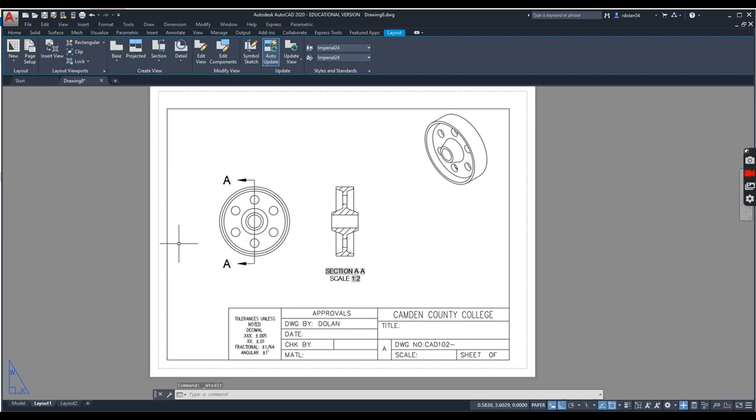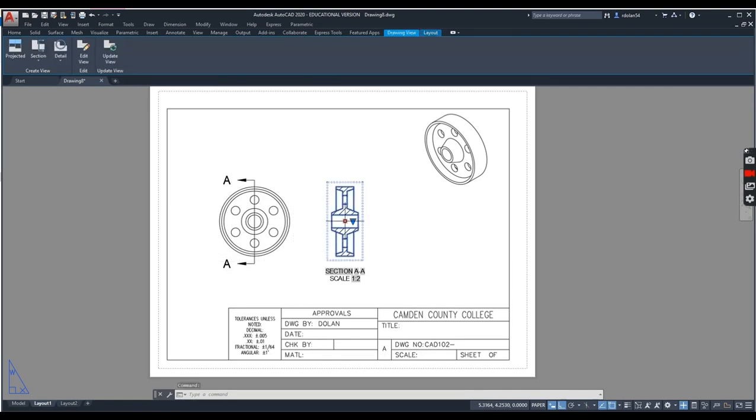Then I would finish dimensioning this drawing, kind of like in the book, 9-19. The thing that you would do differently is that all the dimensions on the right side of the side view of the hub should be between the two views. So you might want to move them around. You can always move a view by just clicking on it, hovering over the square dot, and clicking on it where it turns red. I may want to move it there.